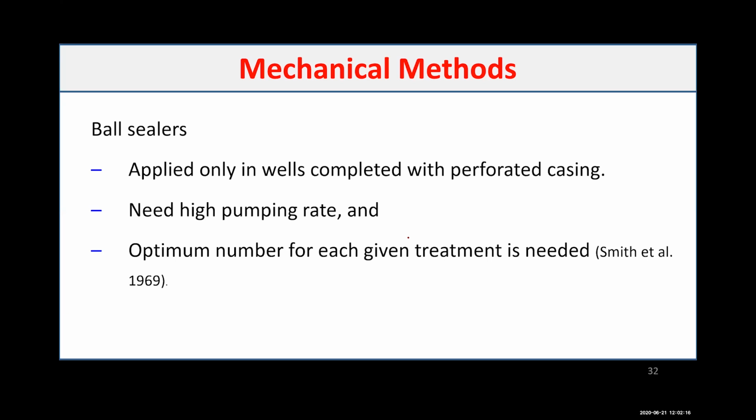There are ball sealers, which again are applied for perforations, but in addition to the mechanical part, they need a higher rate. Ball sealers need a higher rate to be bumped. So you cannot bump ball sealers at a low rate. They will not sit in the perforation.